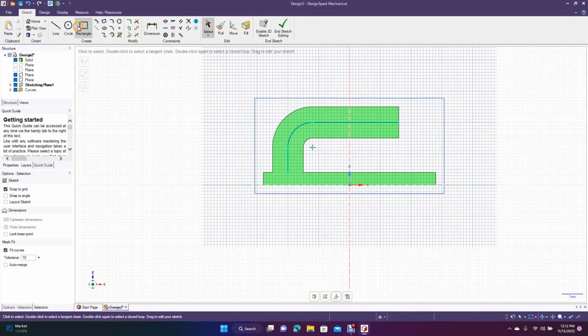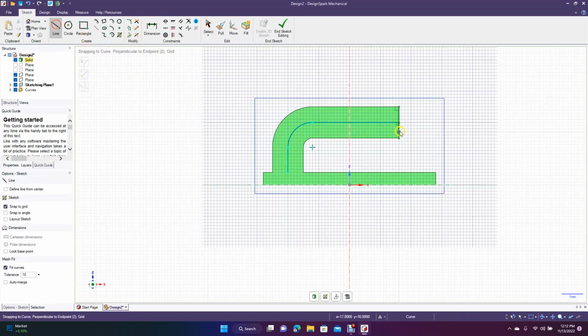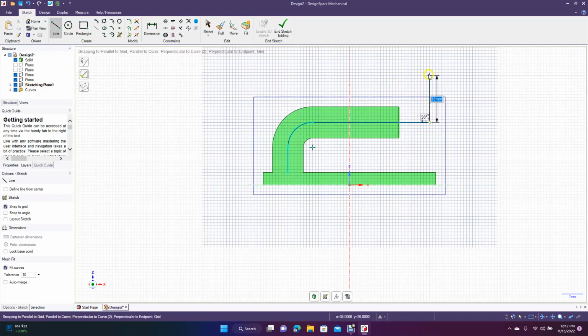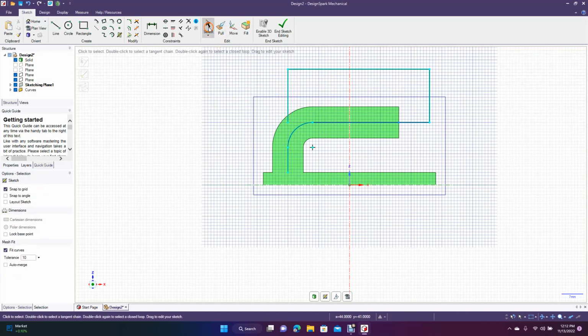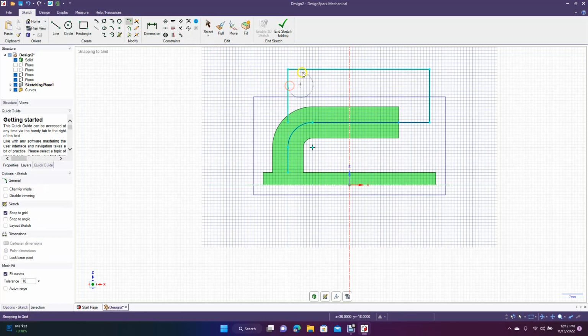So we would go to sketch mode, get the line tool, and then come out here, go up here, come over here. Let's go down in the middle here. So we'll follow that line up, and then come down to here. Let's select and click off. Now we're going to grab our create rounded corners. We're going to put some fillets on these. Let's do 7.